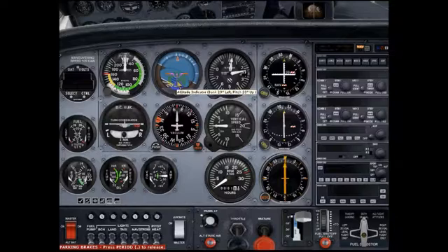This is operated by a gyroscope. So is this one. So these are gyroscopic instruments, the attitude indicator and the heading indicator. This is an electrically operated gyro system. These are vacuum powered. You could see vacuum there and the word vacuum there. So it's telling you, hey, the vacuum system is powering me. This one says DC, which means direct current electricity. So this is an electrically operated gyro.